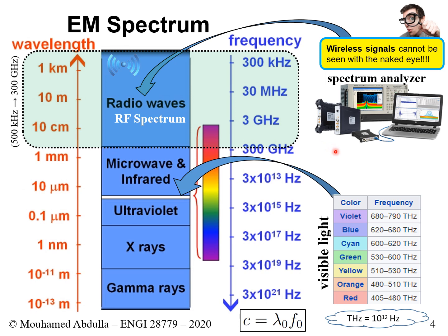If you are looking at a really expensive spectrum analyzer, one that perhaps costs up to $150,000, these spectrum analyzers allow you to see signals that could operate anywhere from 3 hertz, which is a really, really low frequency, up to 67 or 70 gigahertz. 67, 70 gigahertz, that's tremendous. These are very, very high frequencies that are potentially, and in fact they are used mostly by government agencies, but not by civilians. So this is what I wanted to mention.